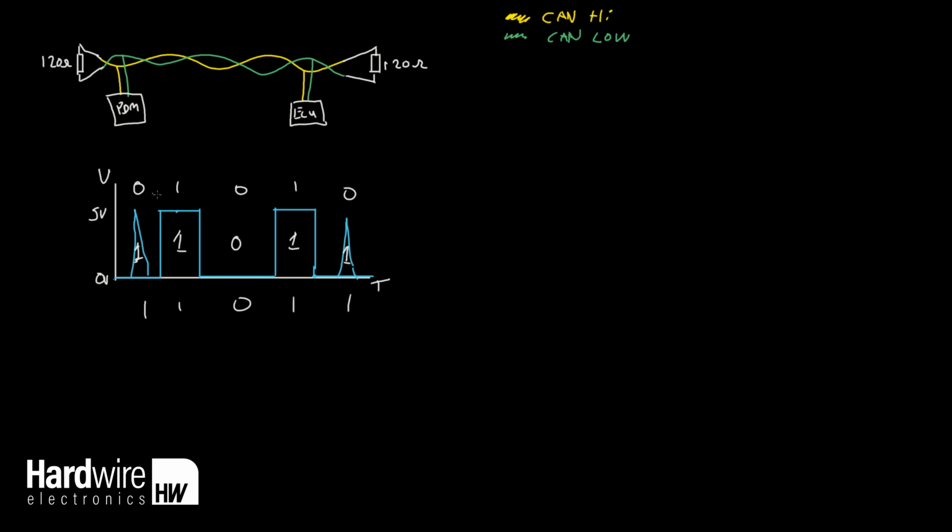Now there are ways around this. We can increase what's called the signal to noise ratio, so we can actually increase the level of the on bit of the 1. So let's say we increase this up to 12 volts, and now at the receiving end, because we are expecting a larger signal, 12 volts for a digital one, these voltage spikes here won't cause us any problem. They will still be registered as a 0. So that's one method you can use to get around this problem, but this means that the transmitter and the receiver now, instead of only having to deal with a 5 volt signal, have to be able to work with a 12 volt signal, and this can cause its own problems.